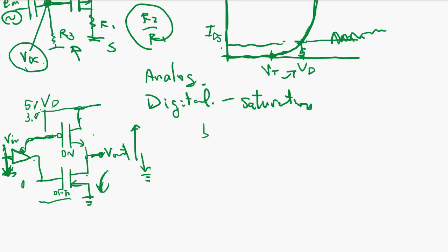They used to be called NMOS. So NMOS is like that. Instead of a P channel, you use a resistor, and you can do the same thing, except that when you turn off this transistor, this voltage goes up, and this is going to be a slow rise.